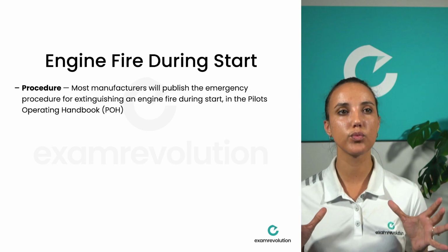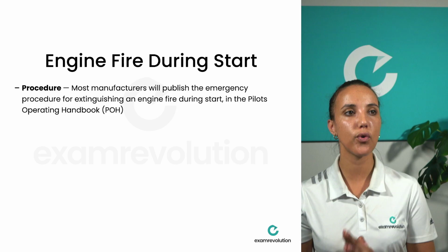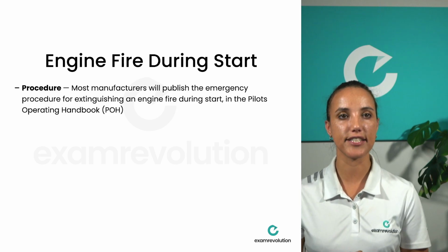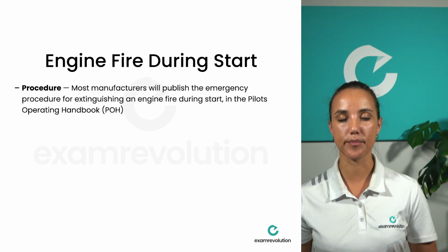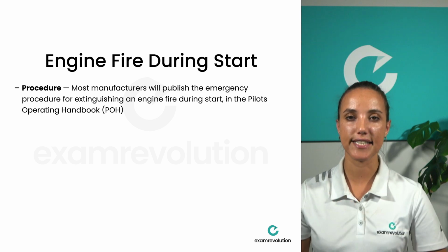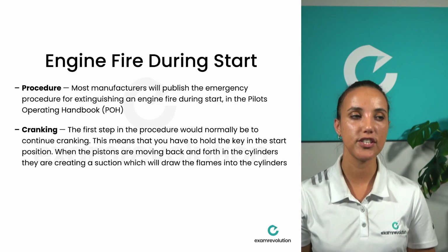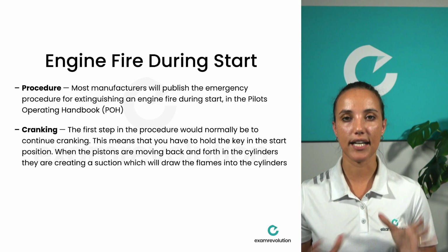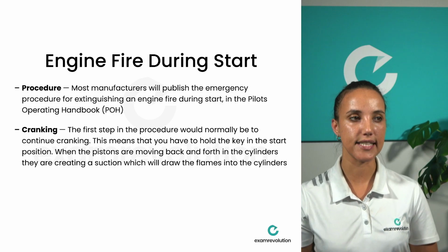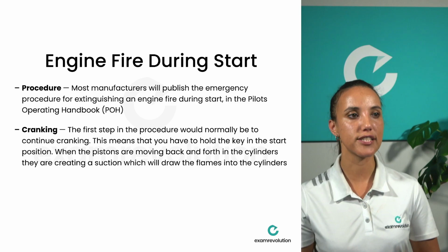Now, most manufacturers will publish the emergency procedures for extinguishing an engine fire during start in the pilot's operating handbook, so you must follow your exact aircraft procedure. This is just a generic procedure that you might find 8 out of 10 times in a pilot's operating handbook. And the first step is always to continue cranking.